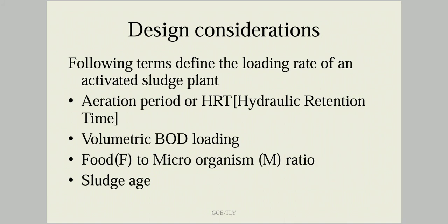Then, in order to design a plant, we need to keep the following considerations in mind. The first one is aeration period or hydraulic retention time. The second one is volumetric BOD loading. The next one is the food to microorganism ratio, and then the sludge age.